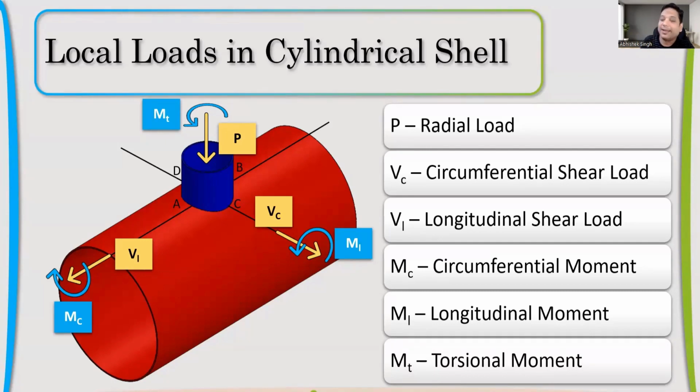At this stage, even if you want to call it circumferential load, it's okay. But if you understand how this load will create which kind of stress, then you can even call it shear. So whichever forces we have called shear load will create only shear. There won't be the membrane force we discussed earlier, and there won't be the bending stress we discussed earlier. So membrane force and bending moment will be because of what? Can you summarize which among these nomenclature will have membrane force and bending?